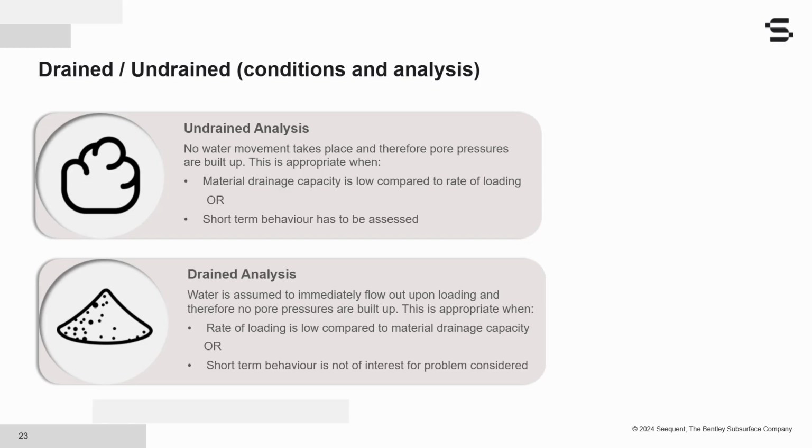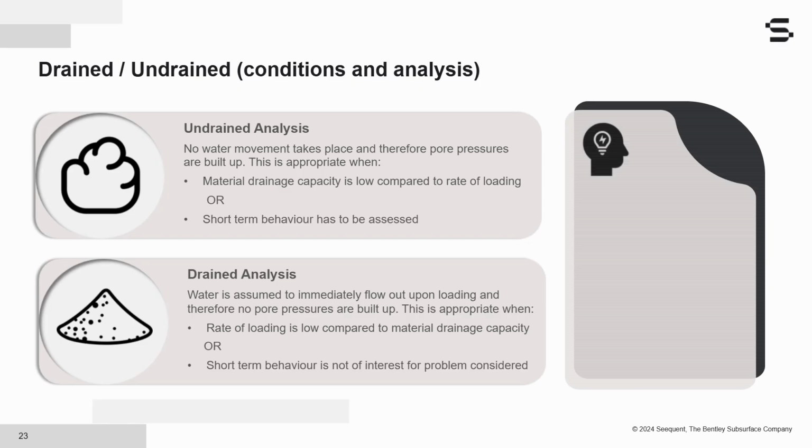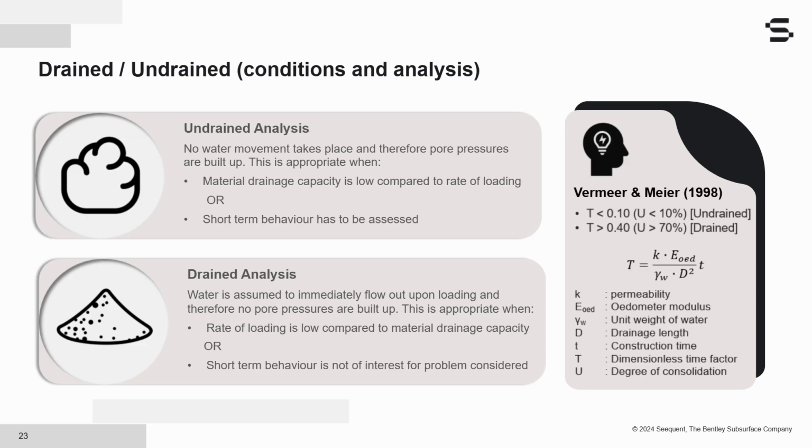Now, as we said, if the rate of loading is sufficiently high relative to the soil permeability, such that no significant dissipation of excess pore pressures occurs during the loading itself, then an undrained analysis is appropriate. As we said, for most practical cases, this includes construction activities in stiff clays. However, and this is something that I need to underline here, it is wrong to assume that all clay soils behave in an undrained manner. For example, normally or lightly over-consolidated clays may behave in an almost drained manner because they have quite thin deposits, and maybe they also have sandy or silty laminations that actually shorten the drainage path lengths.